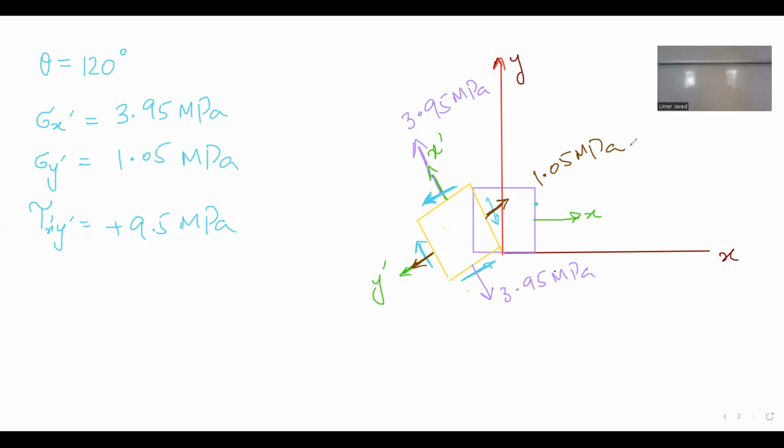Let me ask you. Look, what I'm saying is when you have tilted, just identify the x prime. Let's say you have identified x prime exactly like everyone helped us. Let's say this is x prime. If someone has given you tau x prime, y prime, a positive value, then on this surface you try to make an arrow in the anti-clockwise sense.